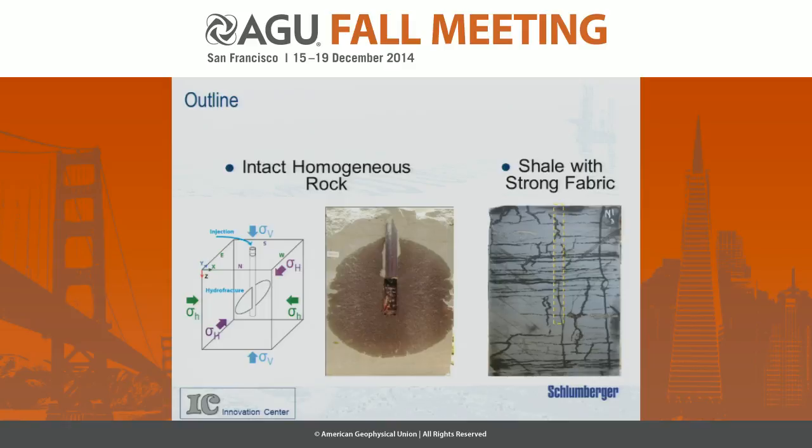On the right side of the slide, you can see the photo of the shale surface before the test, wiped with odorless mineral spirits that evaporate very fast from a smooth surface, highlighting the structure of pre-existing cracks and bedding planes. And we investigated in our research the influence of this complicated rock fabric on the properties of the created hydraulic fracture.